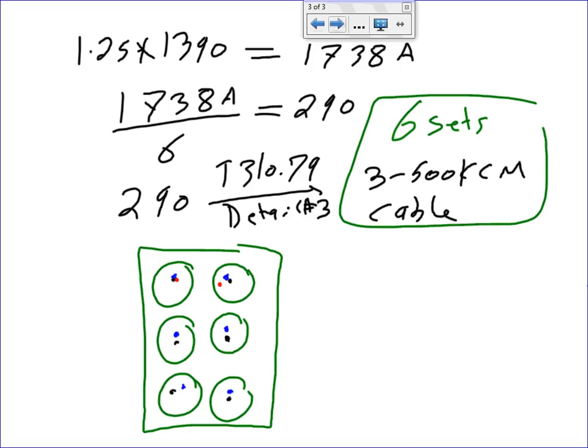Here's the phases, all the 3 phases. And you know what they did with them, guys? I don't have another color, so I'm going to put a cable. And then they cabled them. All these are cabled together. Does that make sense? They're one cable, multi-conductor cable. So that's detail number 3. Multi-conductor cable we pulled, then we carry this set. 6 sets.